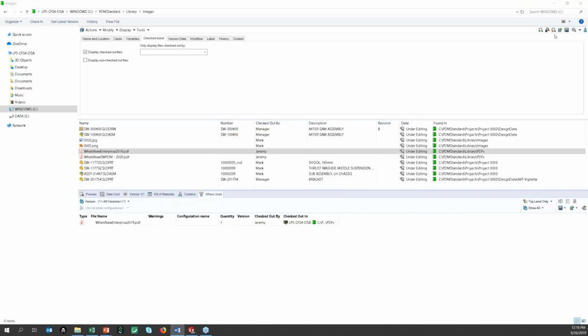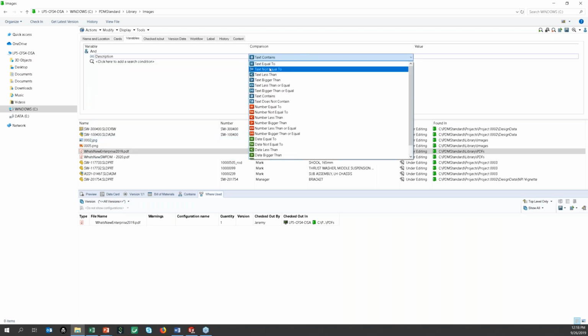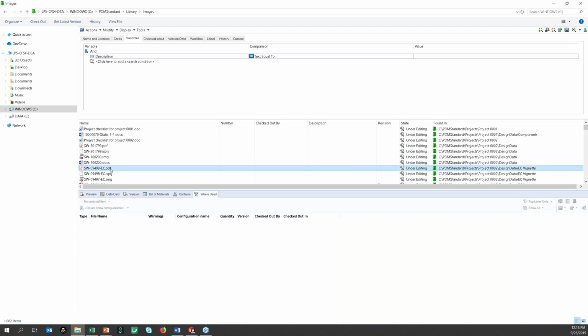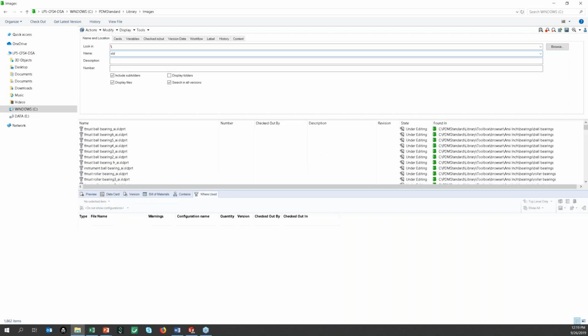What if I want to refine my search and see if there is any description that is not populated in my files, because the description is important for my bill of materials. By running this search, I can see that I found about 1,800 files where the description is not populated. I can actually narrow down this search to SOLIDWORKS files only. So I can just type in SLD, the beginning of the SOLIDWORKS extension, and now the system literally just filters that information down for me.